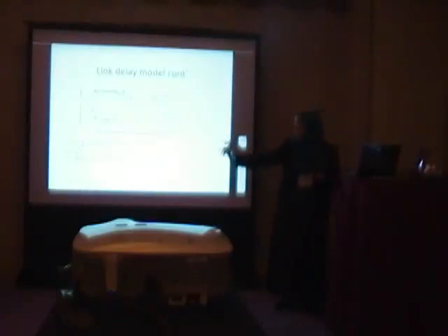So if the delay is a function of R and C, which in turn are functions of W and H, and V threshold and L, if we have as an input to Hessian the standard deviation for the input variables, Hessian will give us the standard deviation of the delay. And if the standard deviation of the inputs is random, the calculated component is the random component of the delay.